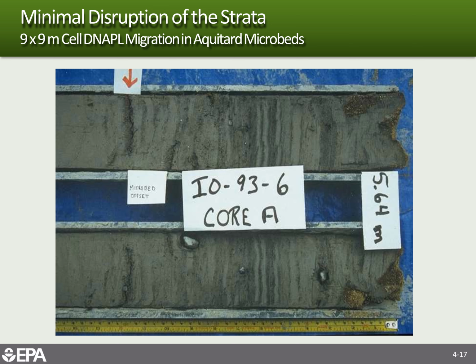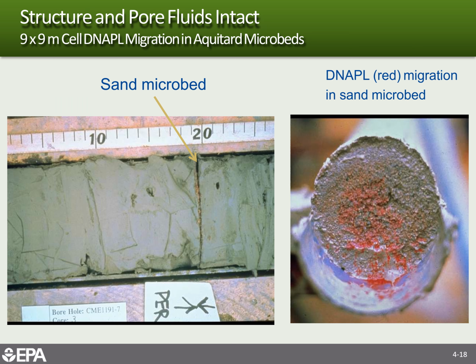That permeability difference might make a difference in how the NAPL or the contamination moves within an area. So this level of detail can be important, because it all moves from pore throat to pore throat, between the sand grains. So it's important to have high quality data.